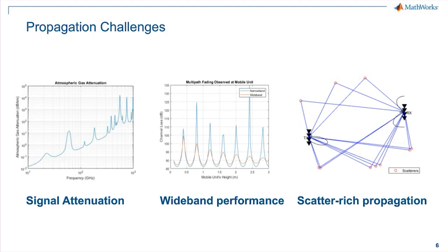About the scatter propagation, we're going to use the scattering to our advantage, but then the traditional channel modeling and propagation based on MIMO channels, Rayleigh, Ricean, which assume a kind of uniform propagation through the air, will have to be replaced by a ray-based optical communication, spatial communication, where you have a one-hop or two-hop reflection or refraction between the antenna array and the received signal. So that is a new set of challenges for propagation. We're going to talk about that soon.